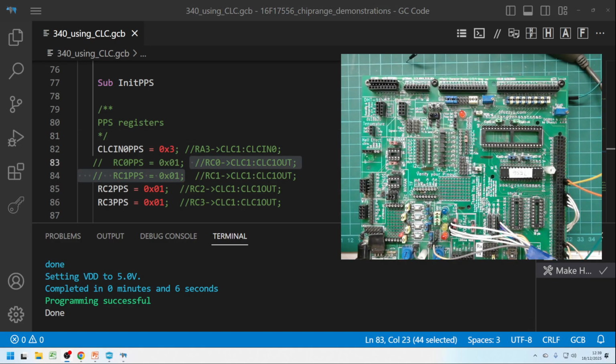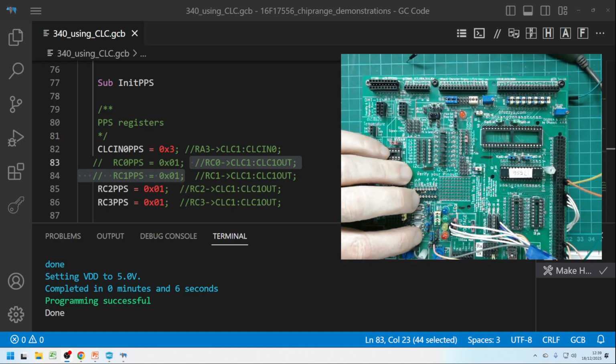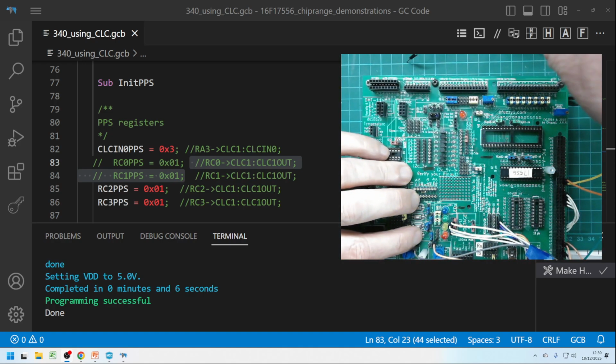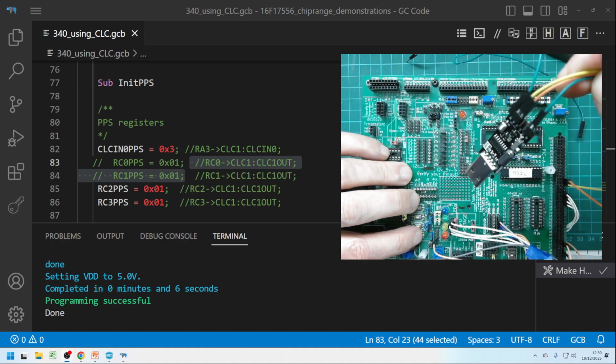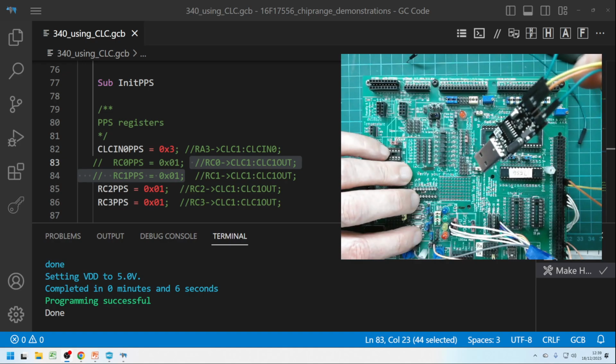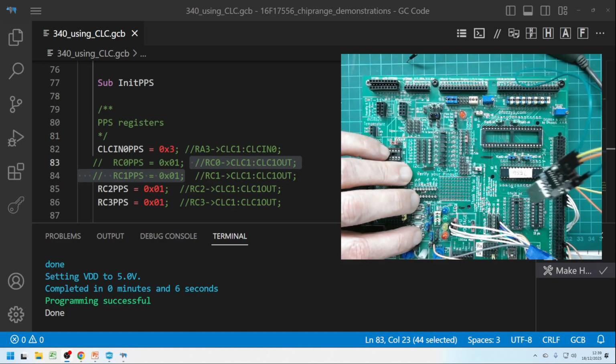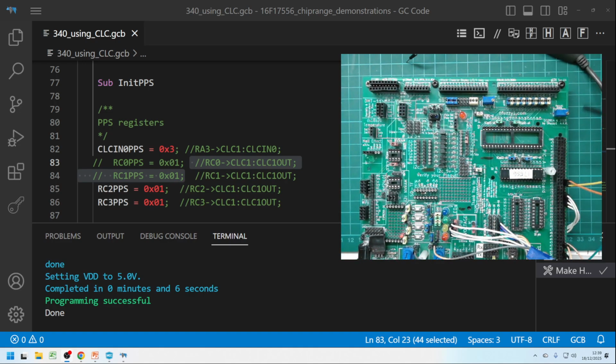Resuming the video, I'm just going to show you a little trick. It's working. The reason why it didn't reset it, because it wasn't power cycling it. I had this plugged in. The USB TTL was using parasitic power. It was putting enough power into the microcontroller, so it didn't actually do a power cycle. Look, so what I did is I've commented out 2 CLCs just to prove to you it's working.